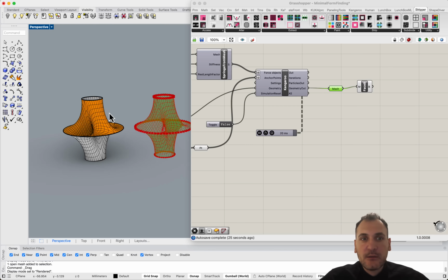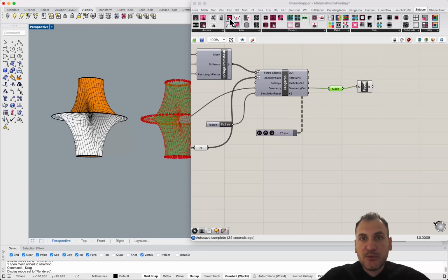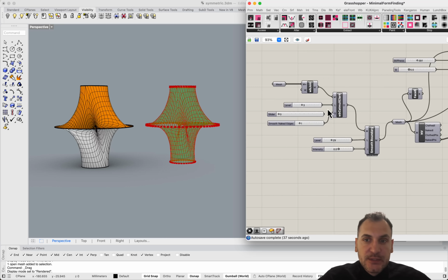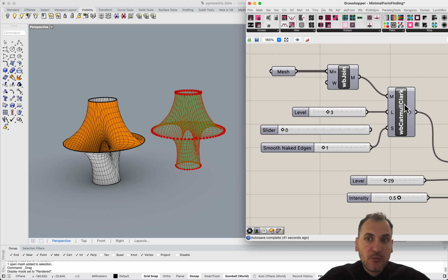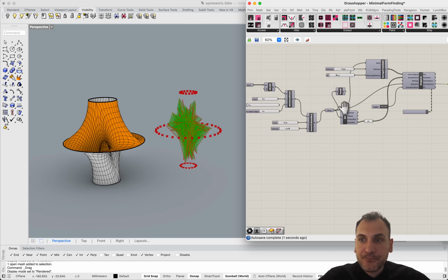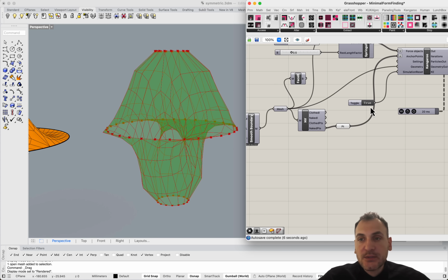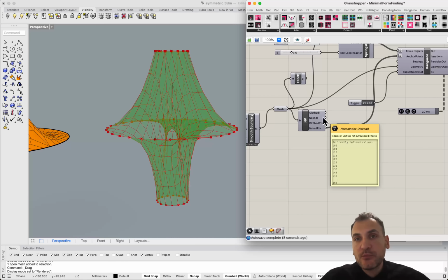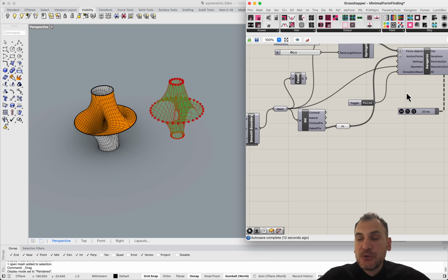So we start with those quads, but those quads get segmented into multiple faces, and they help with the physics simulation. So I'll just show you, for instance, if you have less segmentation. So let's say we don't do 3 levels of Catmull-Clark subdivision, but just 2 levels. And you will see that we have less faces here, right? So that will affect how much the form could be relaxed. But this is essentially like a resolution issue too.